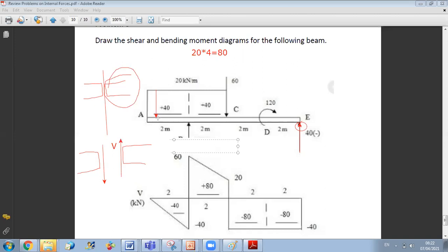This convention is regardless of how you split the forces. Whichever part you take, left or right, you should get the same result for V. If you take V positive in both cases, you will get opposite results depending on whether you take the right section or the left section. Then whatever you put on the diagram, you should have the same value in both cases.